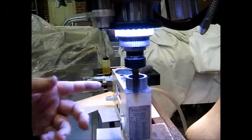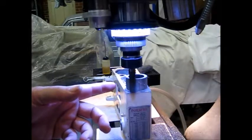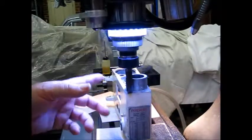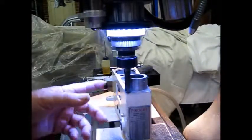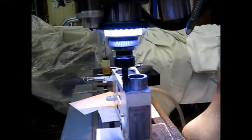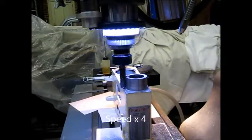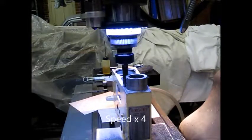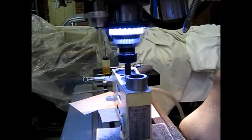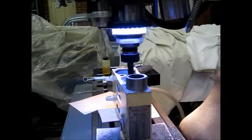So the radius now has been reduced from 35 to 34 millimetres, and our cutter and feed rates seem to be working fine, and I'll type in the next instruction to handle the next 180 degrees. We're getting the side here now cleaning up with this cut, which was what I was after. You can see the 1mm step down there.